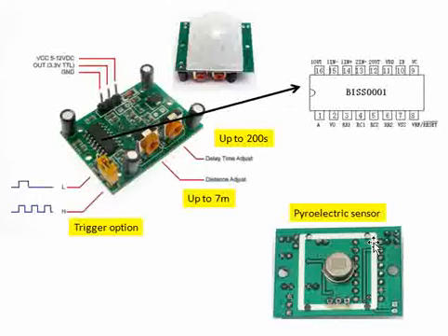While we are talking about the electrical voltage, whatever is generated from the sensor needs to be converted into a realistic voltage which can be read by embedded circuits, right? That's the functionality done by this BISS0001. You can refer to its datasheet, which also gives the embedded circuit in this chip. Ultimately, this is the chip which gives us the voltage. We give supply to this, and it reads the electric output,